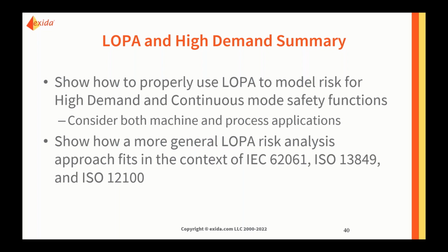And I will admit, almost always that this math is simplified so that even if our safety function is demanded every couple of months, the high demand consideration of that function is going to be a better mathematical model of that situation. And our safety function as initiating event, even with a couple of months of time between the demands, will still be the better math to present that.